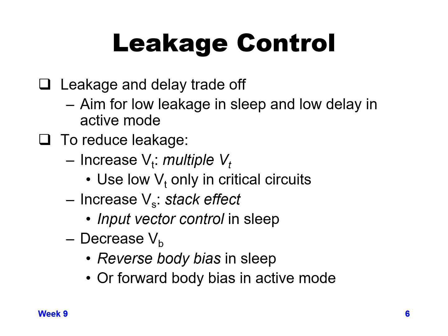And typically less than 10% of your transistors will need a low VT, maybe down to 5% or even lower, depending on the integrated circuit that you're designing. And 90, 95, maybe 98% of your transistors are a higher VT. And if you have a process that has 3 VTs, you might have something like 80% on ultra high VT, 10 or 15% on a high VT, and then 5% or less on a low VT or nominal VT.